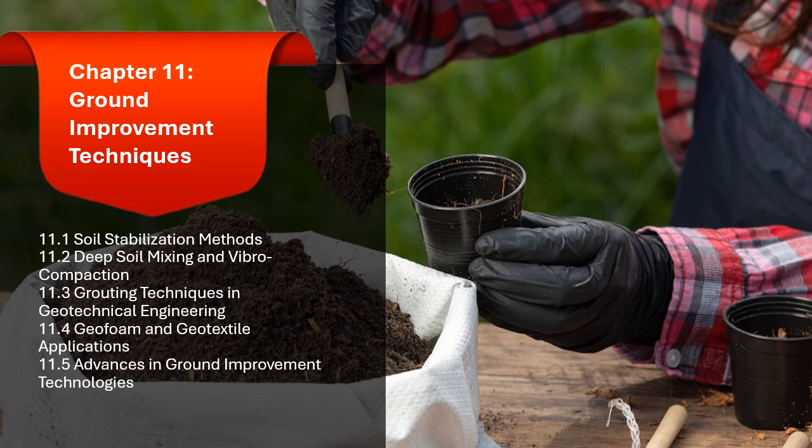1.3.3.5 Tunnel and shaft construction. In tunnel and shaft construction, grouting techniques are employed to control water ingress and to stabilize the surrounding soil or rock. Grouting is used to create watertight barriers around the tunnel and to prevent ground movement or settlement that could affect the tunnel structure. Jet grouting is often employed in such applications for deep ground treatment.